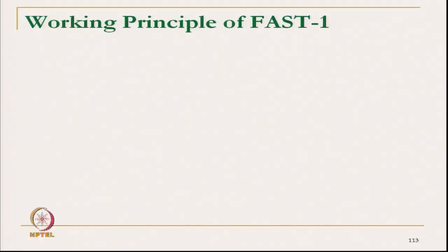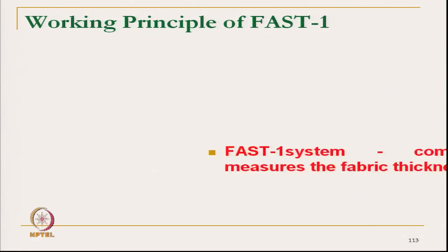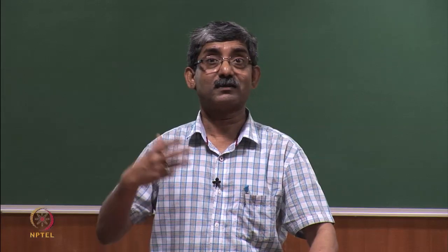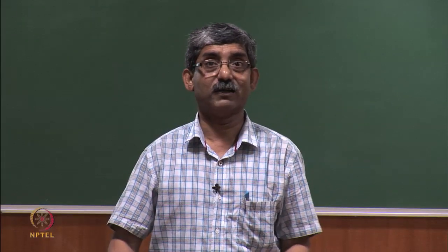Now, let us see the working principle of the first one. It is a compression meter, it simply measures the fabric thickness and nothing else, but let us see how we get a large amount of very nice information.